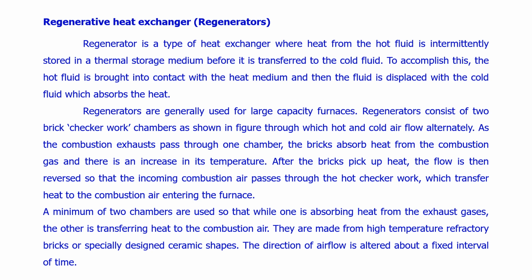After the brick picks up heat, the flow is reversed so that incoming combustion air passes through the hot checker work, which transfers the heat to the combustion air. That is, two-way heating is taking place like a counterflow heat exchanger. The brick absorbs the heat and releases the heat. The brick will hold the heat for more time. Retention of heat in the brick is more. That is, the retention time of heat in the brick chamber is high. That's why they are using the brick type of covering.